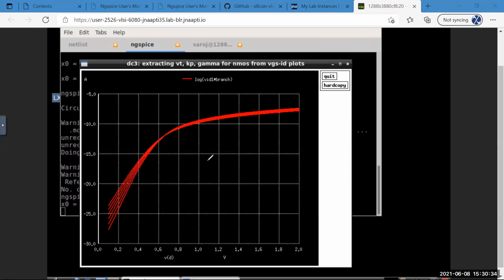So basically, this is all what we sort of predicted in our session in the morning, and we're just sort of verifying it. So basically, we said the mu decreases with higher temperature. So we saw that because the slope is decreasing, and when we do the Python script now, we'll calculate it and see it as well. And then the VT decreases with higher temperature. We saw that the intercept was at a lower voltage. The subthreshold current we saw is increasing with higher temperature, like we see here, but the slope is decreasing, like we predicted.